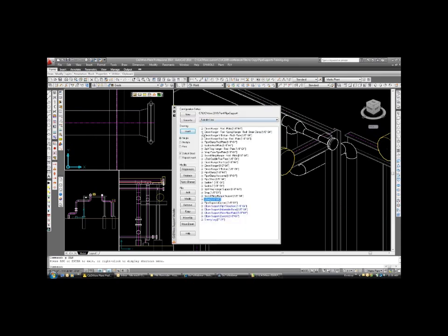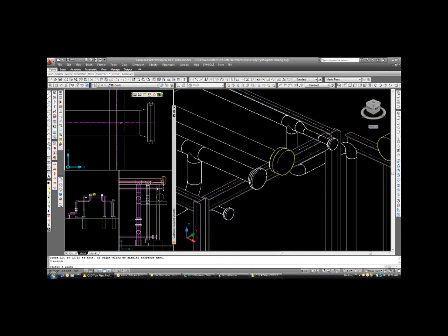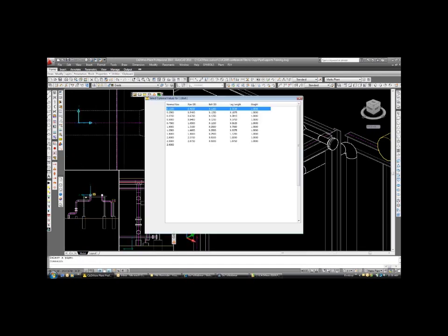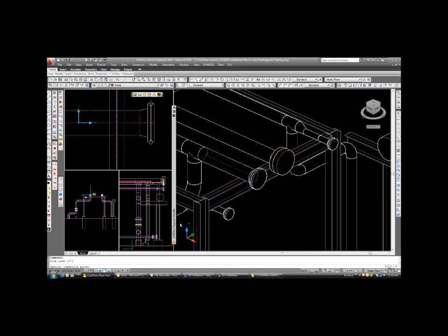You notice I'm just selecting the upper level of the assembly. And I'm going to say detect steel in a single. I'm going to select the pipe and say OK again. And I'm going to pick nearest. Now, with my hands off, I did this right. It should have detected the steel and put the U-bolt in, and it did.